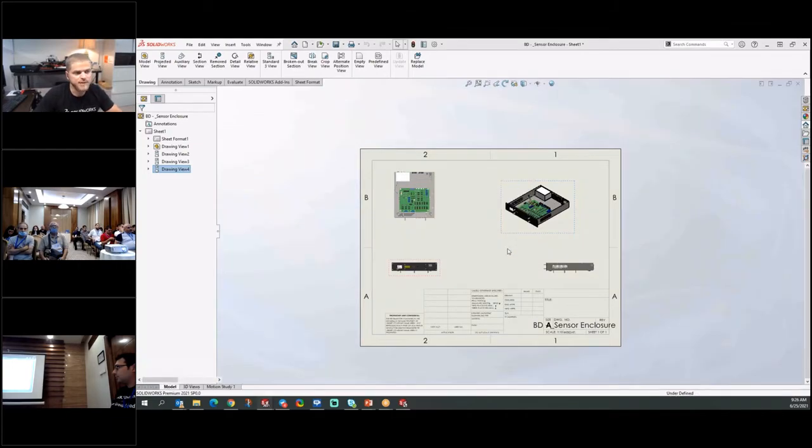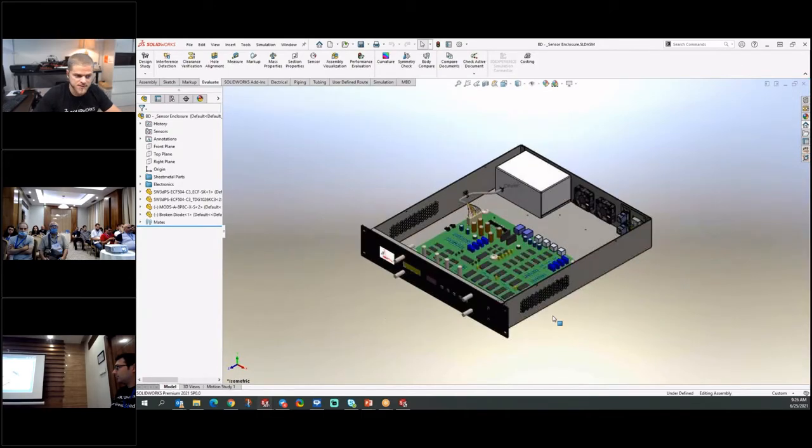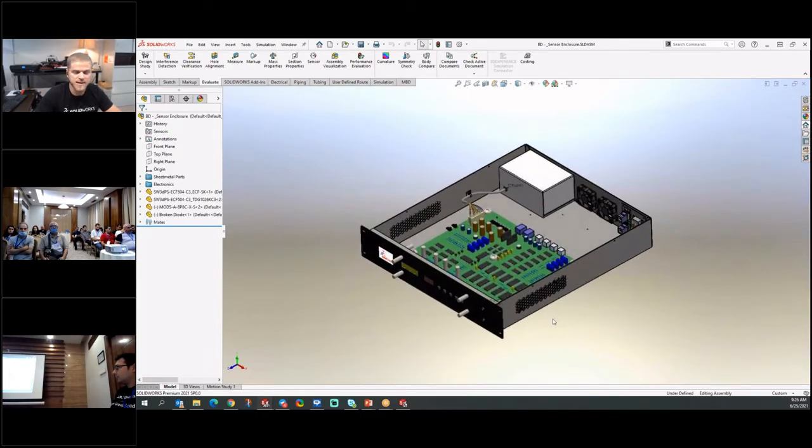And I've seen that before in tech support, and that usually means there's an issue here. There's actually an issue back here in the assembly that's forcing the drawing into draft quality and then forcing the PDF to not look correct. So there's a chain reaction there.